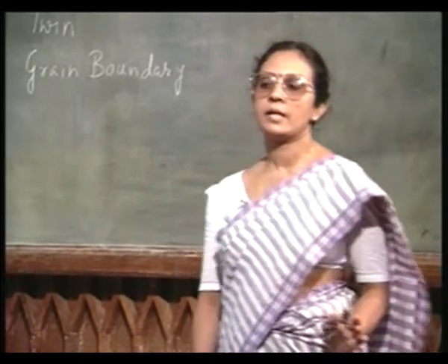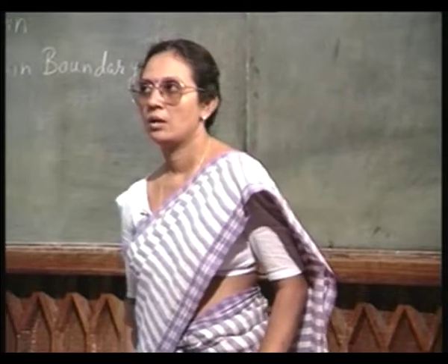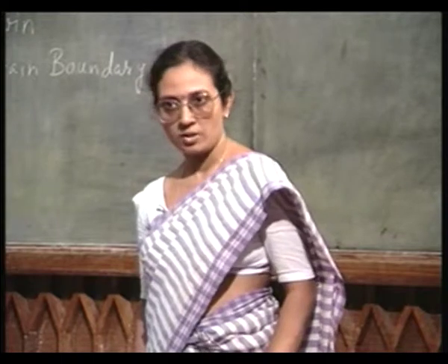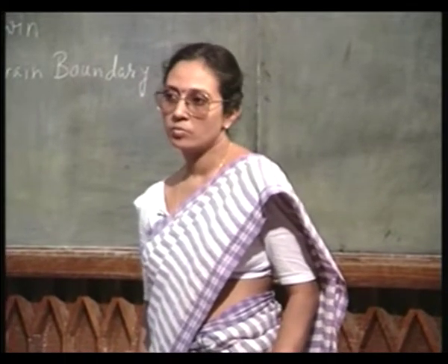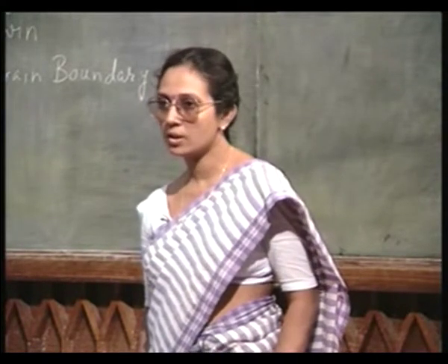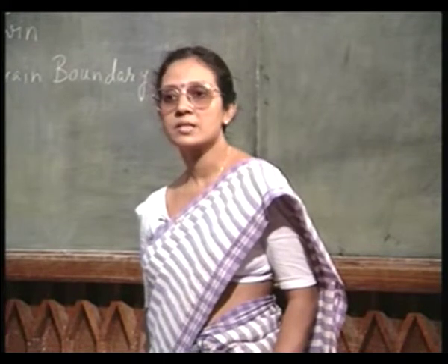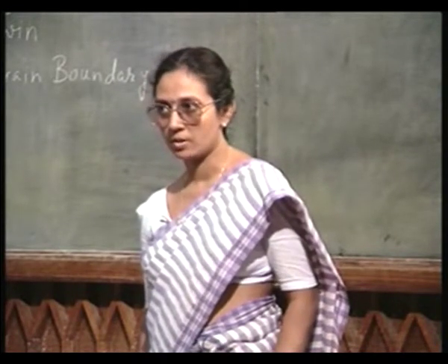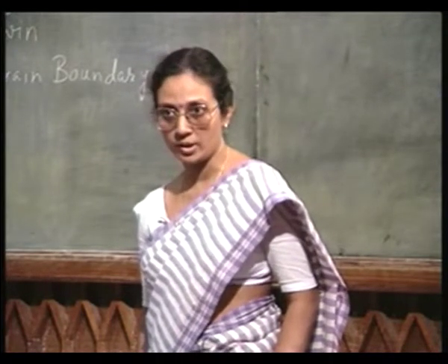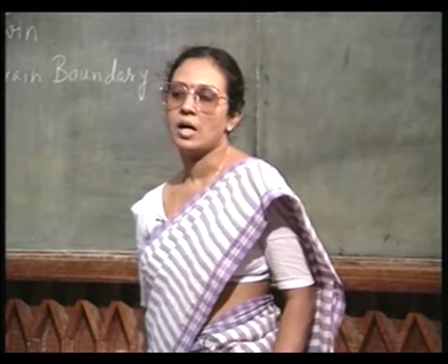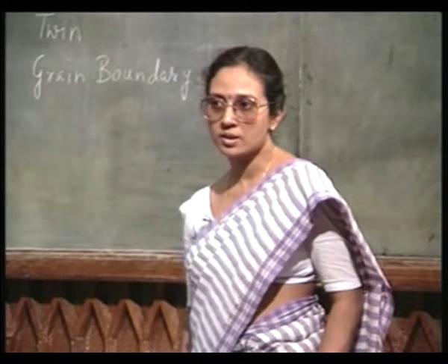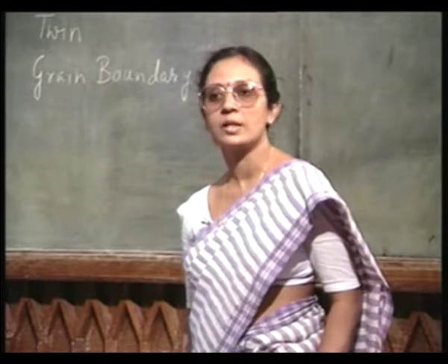In contrast, grain boundary is something else. Our intention is to grow single crystal. But suppose due to some process problem, you have a polycrystalline material. What do I mean by a polycrystalline material? That there are various crystalline orientation in the same substrate, and in between these crystalline structures, which are called the grains in a polycrystalline material, I have a highly defective boundary region separating one crystalline region from another, which is called the grain boundary.